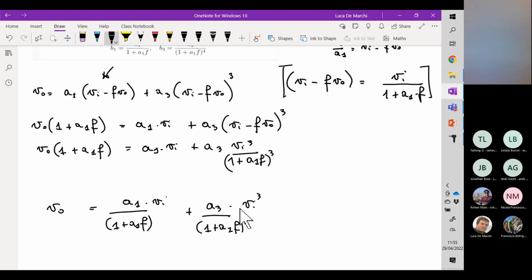And then we can model the output port as the effect of the amplification according to the factor A with respect to the input voltage VE. And then we will have a certain output impedance associated to the amplifying stage. So then we plug this circuit into a feedback loop.